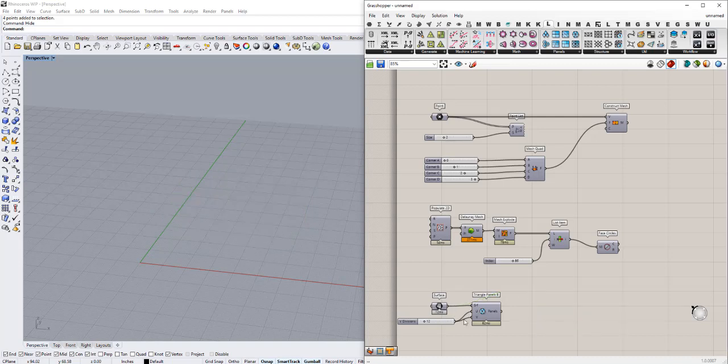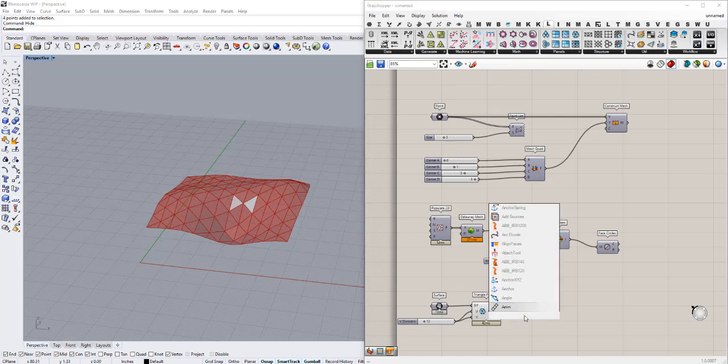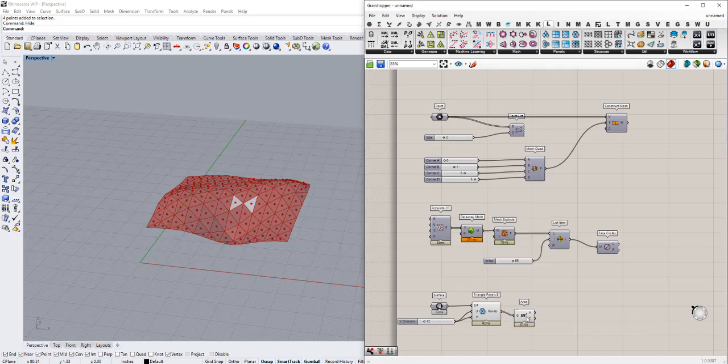And if we want to have more control over these panels, let's continue how we were going. We want to somehow take each one of these panels, and we'll use that as a framework for creating more complex geometry, similar to what we were doing before, or the computational version of it that we were looking at with the provider. So we're going to take each one of these mesh faces. Let's find the center point of that. We can do that by looking at the area of that panel, and that'll give us that center point.